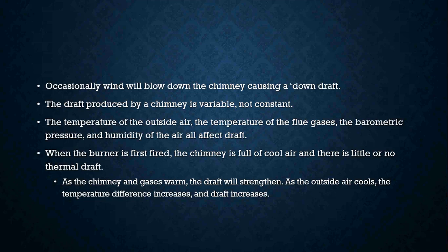Not unless we have the same consistent temperature throughout the winter, which we all know doesn't happen. So it's variable. The temperature of the outside air, the temperature of the flue gas, the barometric pressure, the humidity in the air all affect draft. Now think about that. It's never going to be the same.